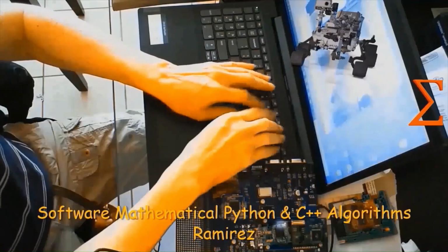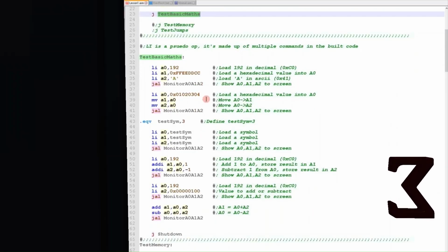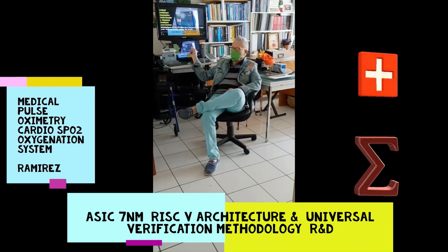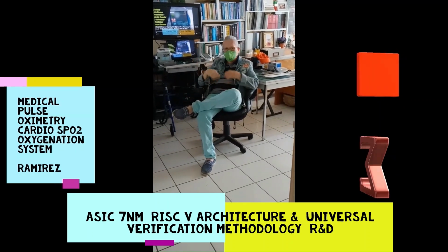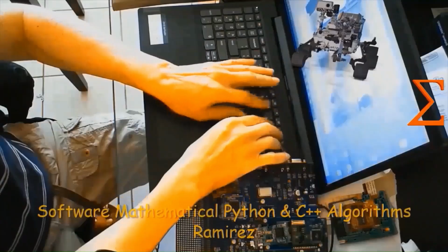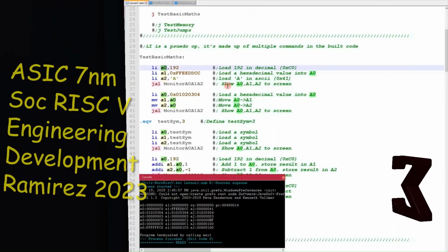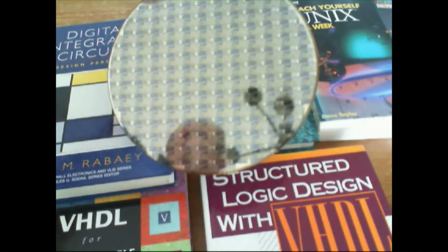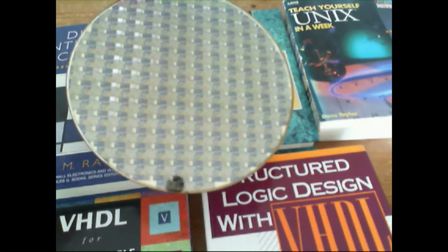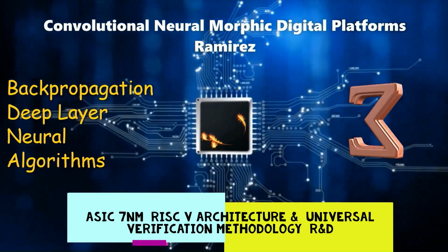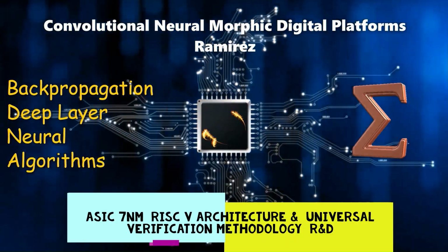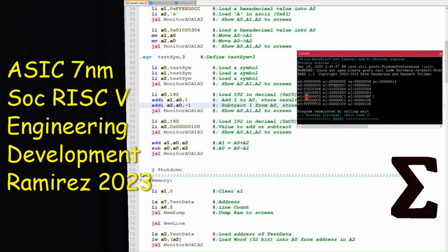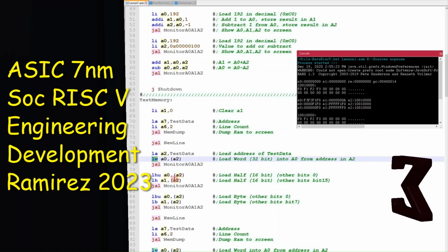Simulation at the RTL and GL level, simulation of the whole chip with scan controller, external controller, logic analyzer, check wait state settings, and check clock divider settings. With respect to scan controller, this test only instantiates user project wrapper, which contains all the small projects. It doesn't simulate the rest of the ASIC.